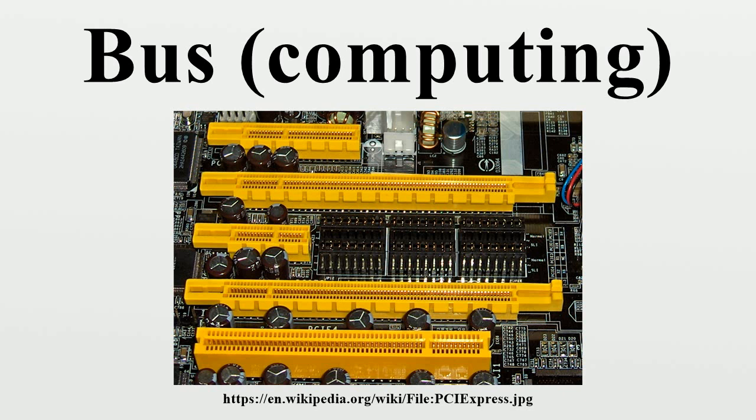Moving from 8-bit parallel buses in the first generation, to 16 or 32-bit in the second, as well as adding software setup to supplant or replace the jumpers. However, these newer systems shared one quality with their earlier cousins, in that everyone on the bus had to talk at the same speed. While the CPU was now isolated and could increase speed, CPUs and memory continued to increase in speed much faster than the buses they talked to. The result was that the bus speeds were now very much slower than what a modern system needed, and the machines were left starved for data.